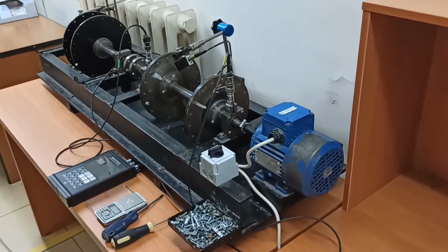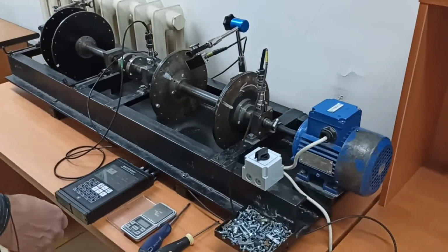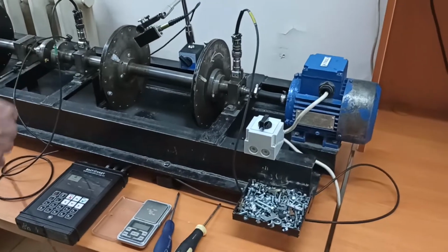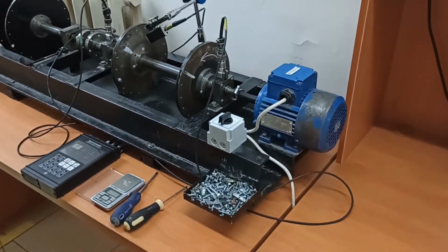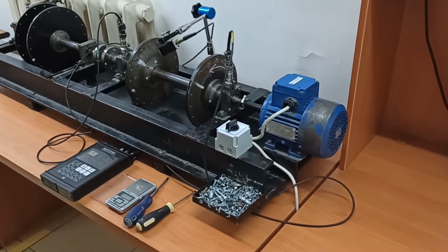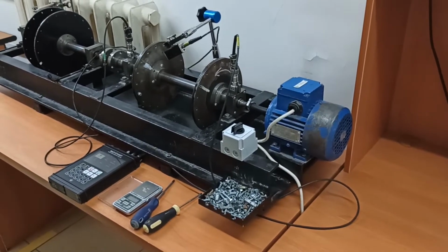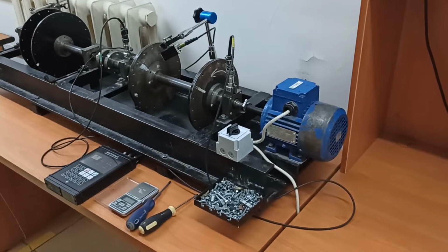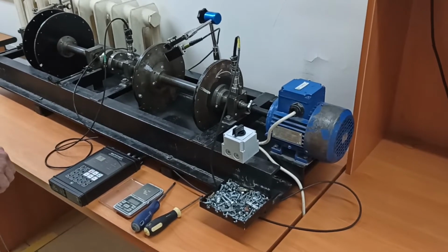So let's start. Initially we have done some diagnostics. We have found that it is unbalance, we have measured autospectra. Also we have measured coast down of the machine to find the best location for the trial weight. This is also quite important. See the previous video how we did it.